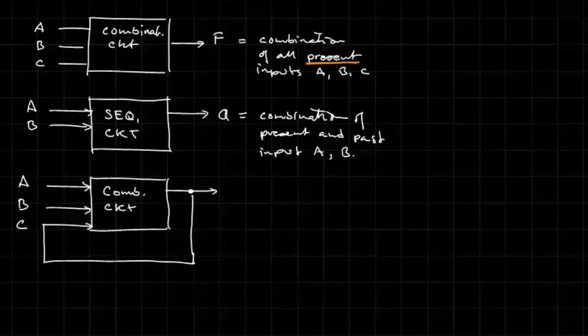Whatever state the output goes to now becomes a logic level that goes back to the input, and that might latch the output to a particular state such that it remains at that logic level even if the inputs A and B should change.